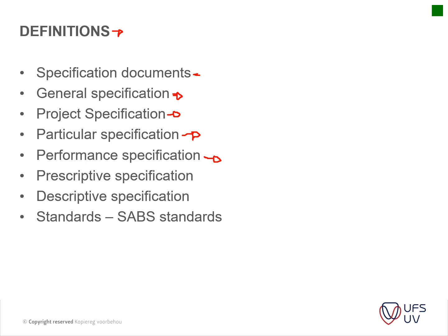That type of specifications. Then prescription specifications, where you would prescribe the contractor to work maybe at night, because during the day it's occupied by tenants and they do not want to be disturbed. So you would have specific prescriptions. Only this access gate may be used during the construction process, etc., etc.